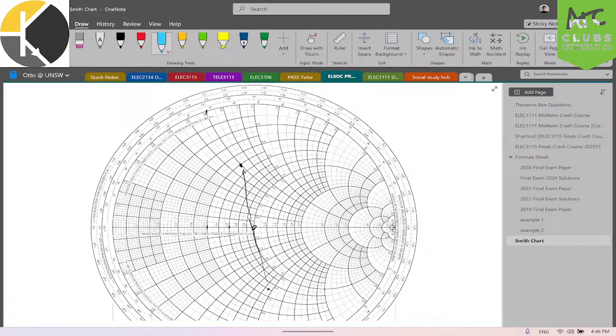So now this diagram is in conductance. I'll probably just use different colors. This is in conductance mode. This is in impedance mode, right? And so what you do, you try to move around the origin until you touch the conductance equals one circle, and then you add conductance in parallel to bring this to the origin, to conductance equal to 1, 0, right? You can find what this section is equal to. To make sure I draw it properly, it is going to be the intersection with the 1.2 line. This point is going to be actually here.